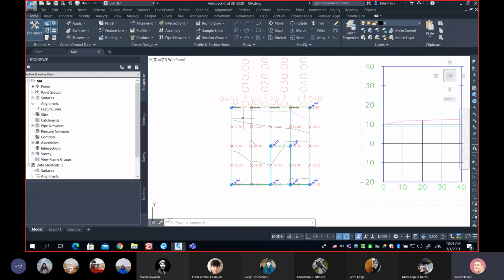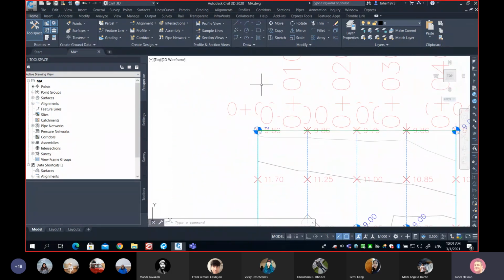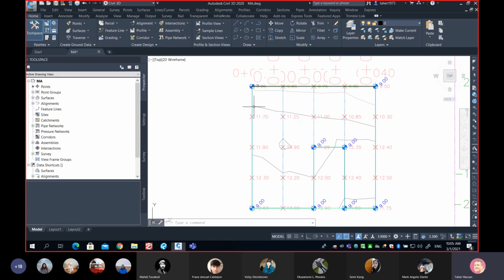If you remember, when I started cutting my sample lines, I needed to add a left swath and a right swath. Those numbers are totally dependent on your choice of alignment. When I chose my alignment on the north side, I needed nothing on the left. You can see I asked for 0. And on the right, I went with 40 meters. As I said, if you were to choose your alignment in the center, then you would ask for 20 meters left and 20 meters right of the alignment.